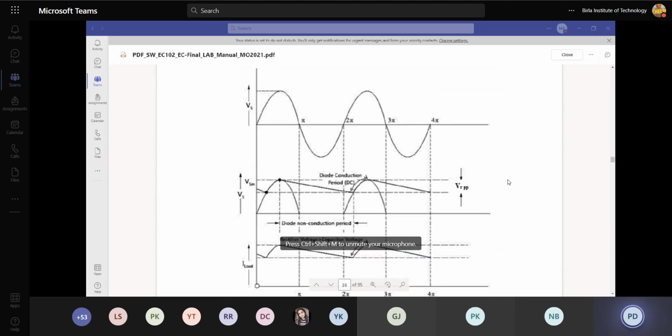Yeah, this one. So this is for the half wave rectifier. If you apply the input source voltage like this, you get a pulsating DC waveform like this. For the negative half cycle, the voltage will be zero, and for the positive half cycle, we get the waveform. But it is still not a DC signal because it again has a time period of 2 pi. Obviously, a 2 pi time period means there will also be a frequency, but DC should have frequency 0. So this is the case of your rectifier output.